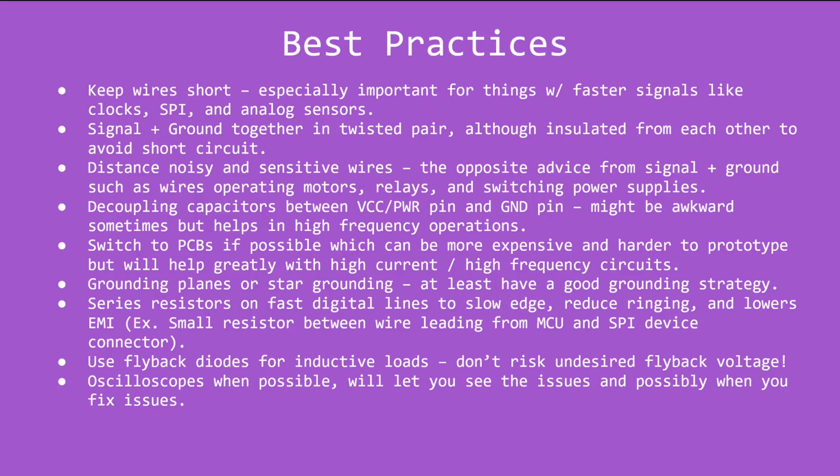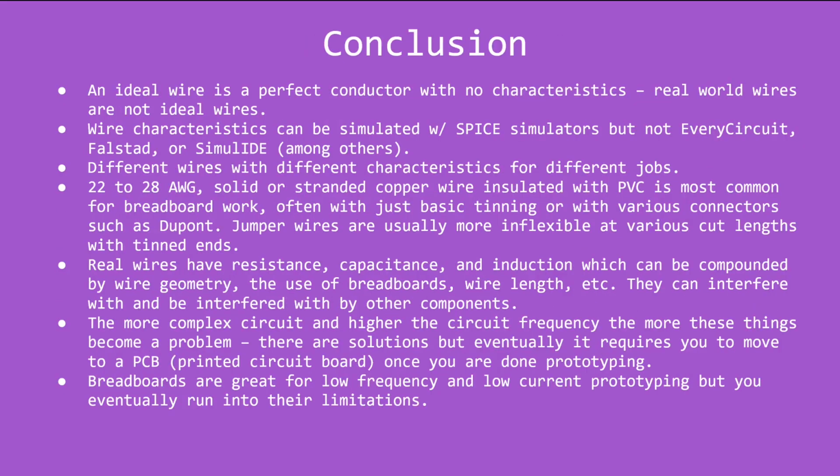I also can't emphasize this enough: use flyback diodes with inductive loads. Don't risk a certain undesired flyback voltage. Lastly, get yourself an oscilloscope. This lets you diagnose issues and see what happens when you better your practices.